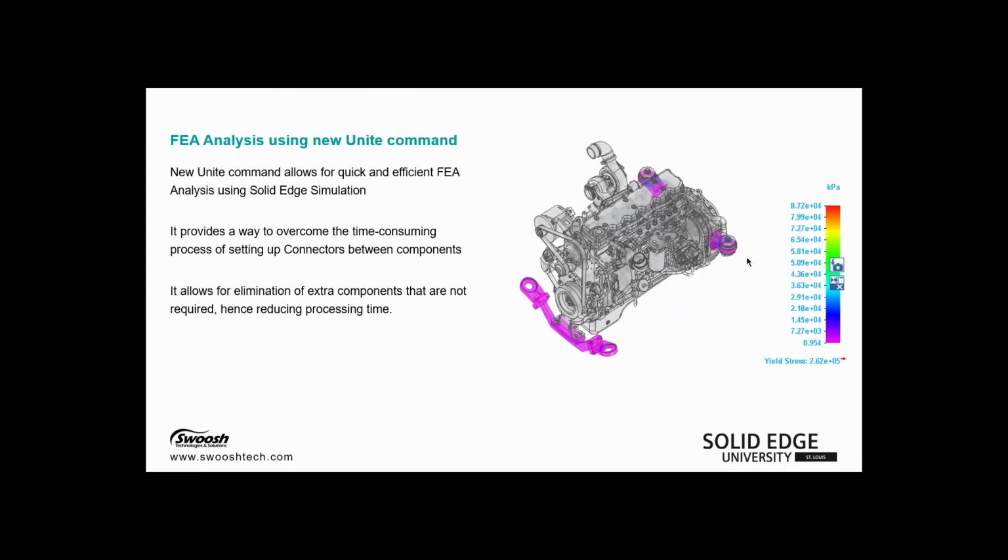The next step, we're going to take a look at how this new Unite command that is available in Solid Edge 2023 will help us analyze quite complex geometry. And while doing that, we don't have to spend extra time on defining additional geometry when we go through setting up this study. It provides a way to overcome time-consuming process of setting up connectors also, because you'll be able to unite all this in one single body. And also we eliminate extra components that are not required. We're reducing processing time. We get to results quicker.